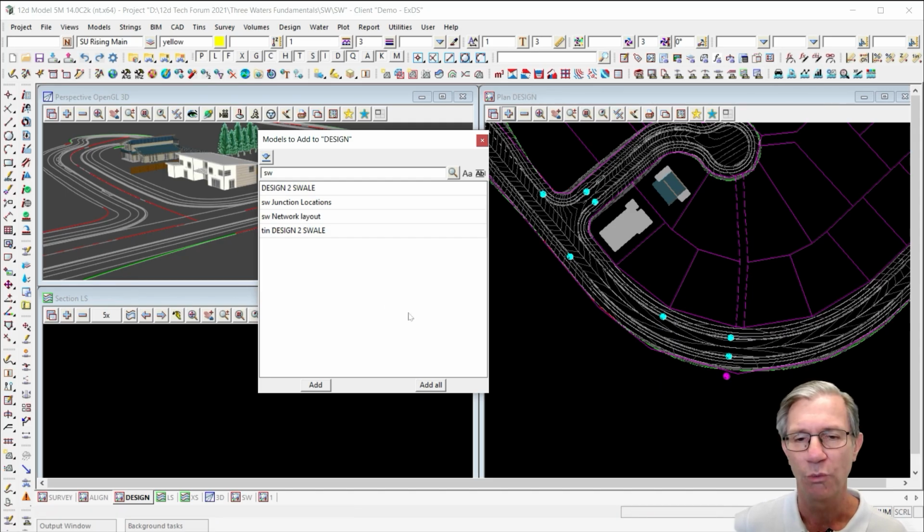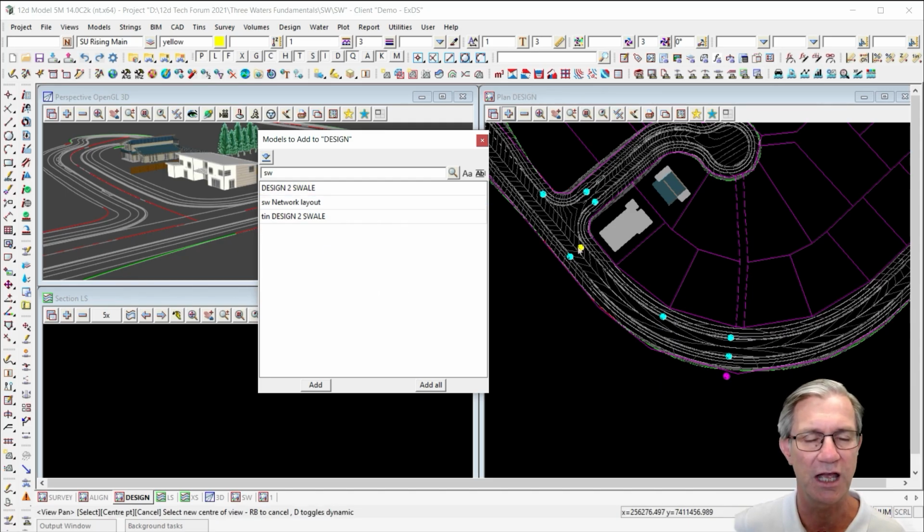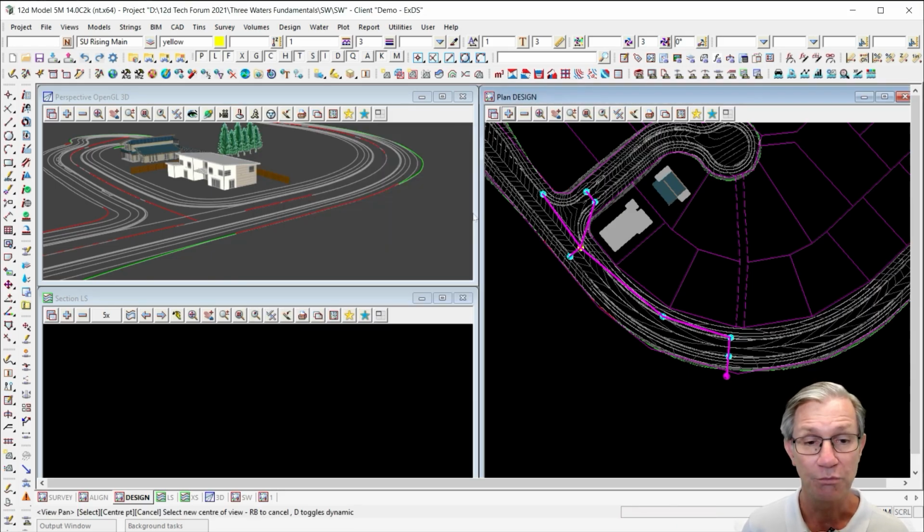Okay. We're going to put in one junction pit for this network. It's going to sit there, and these inlets are going to connect to this junction and carry on to the east. And we'll have a network that looks something like this when we're done. So this is my plan, to put this together in a series of stormwater drainage lines. Before we create the lines, we need to tell 12D what's going to be created, what type of node, what type of inlet, and what type of link, what type of pipe.